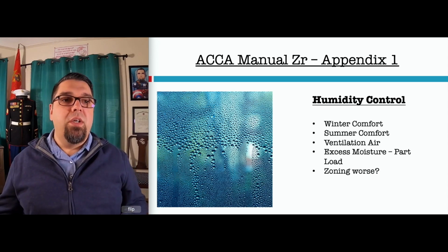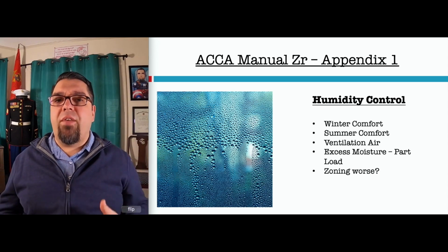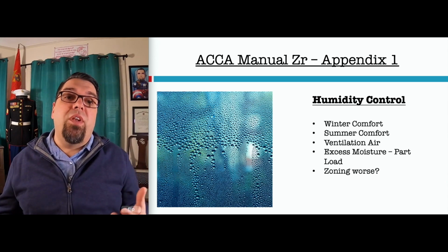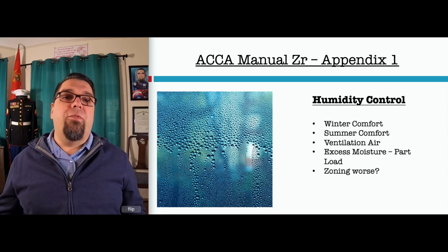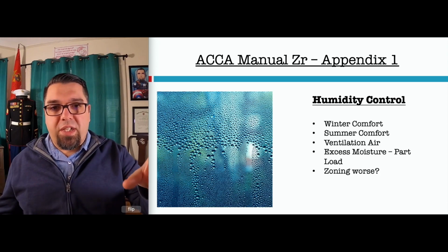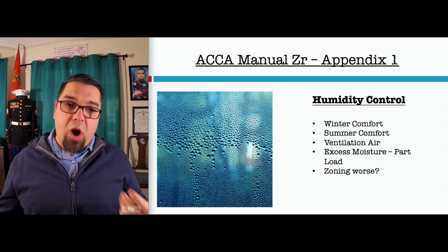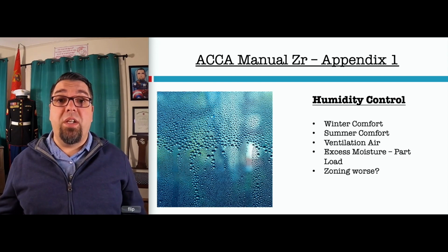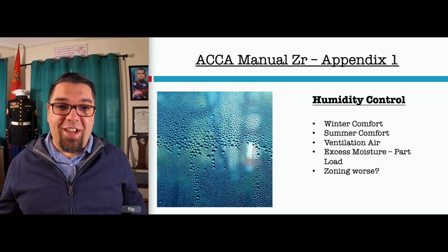That's worse. In the summertime, obviously you're going to have a comfort problem if you're not removing moisture. You almost, especially in the Northeast, can't remove enough moisture in the summertime in order to feel comfortable. And that's why people start turning their thermostats lower and lower and lower. If you have a properly sized system that runs all the time, 75 degrees and 50% relative humidity is actually pretty cold, all right? Nobody's going to believe you when the relative humidity is 55, 60% and you feel warm.